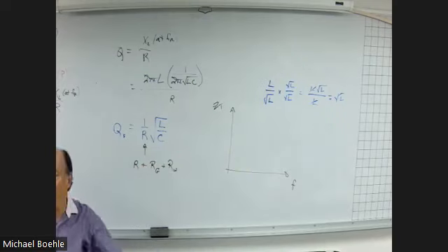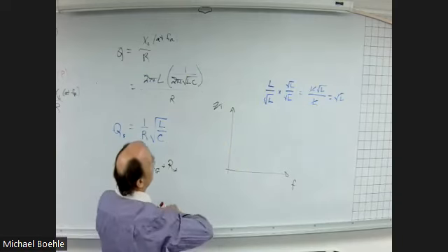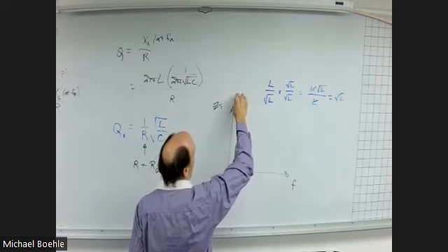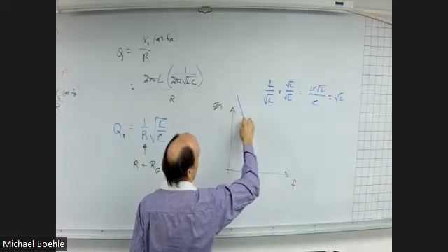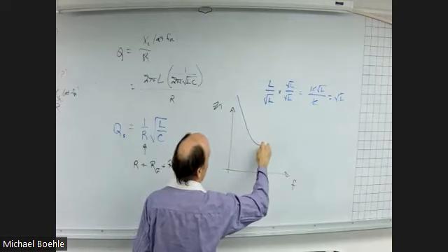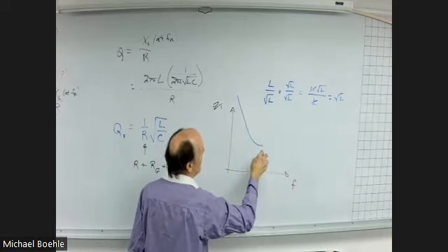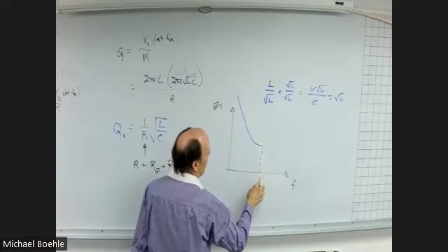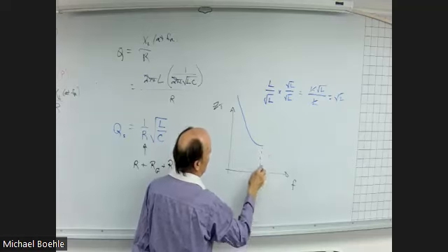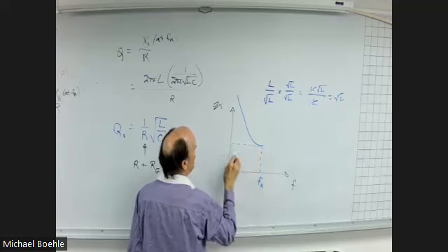As you approach zero, it approaches infinity. So our total impedance starts off at low frequencies really high. Then it starts to drop. And then, of course, eventually it reaches a minimum at that resonant frequency. What is that minimum impedance going to be?